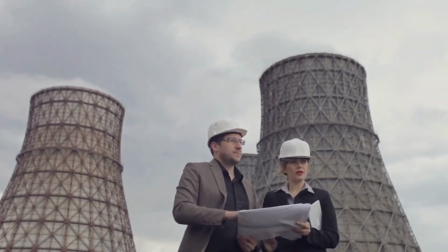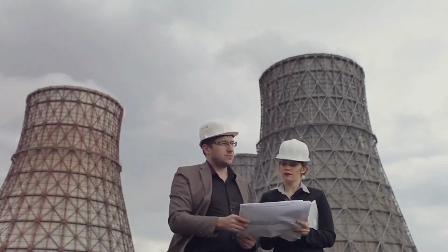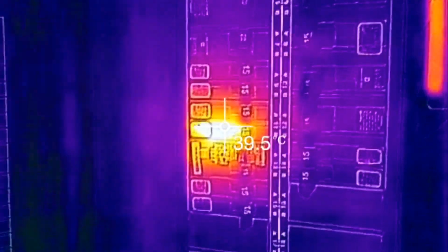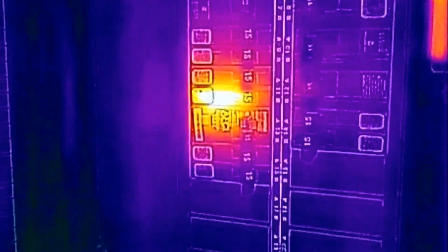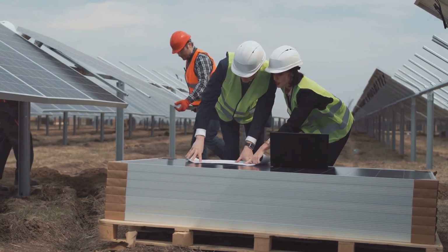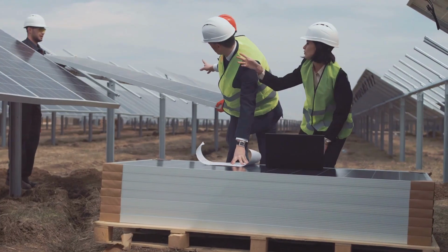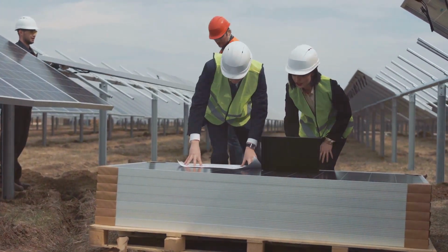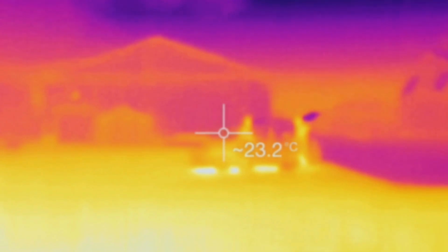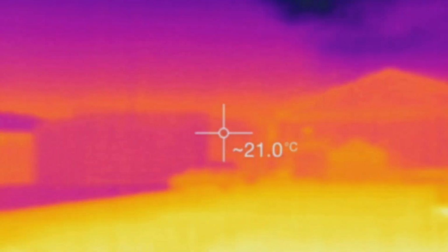Let's explore some of the key radiation models in FLUENT's arsenal. We'll delve into the intricacies of the Surface-to-Surface (S2S), Discrete Ordinates (DO), Discrete Transfer Radiation Model (DTRM), P1 Model, and Rosseland Model. Each model offers a unique perspective on how photons travel and interact with their surroundings. By understanding the principles behind each model, engineers can make informed decisions about which one best suits their simulation needs. This selection process is crucial for obtaining accurate and reliable results.